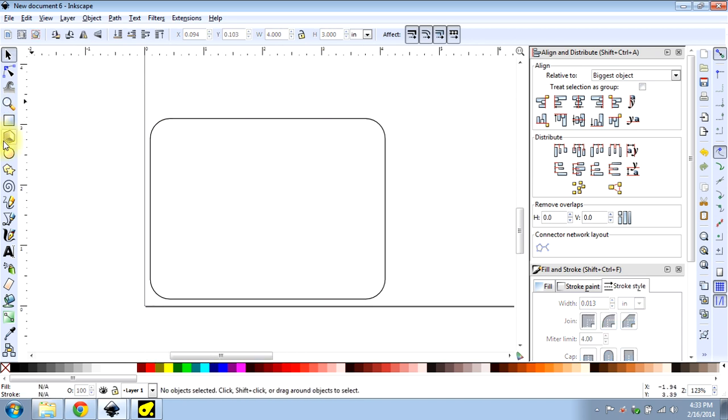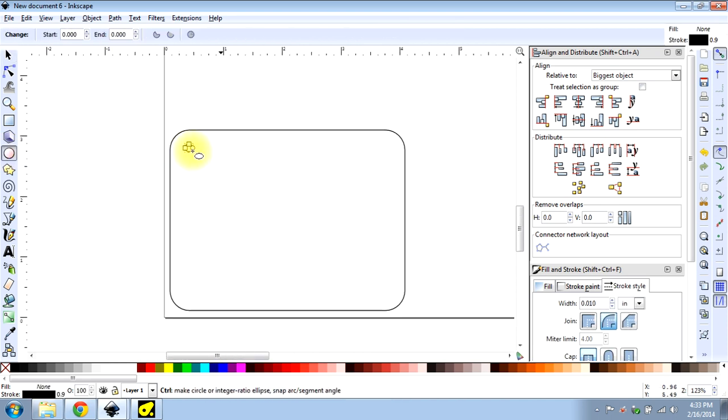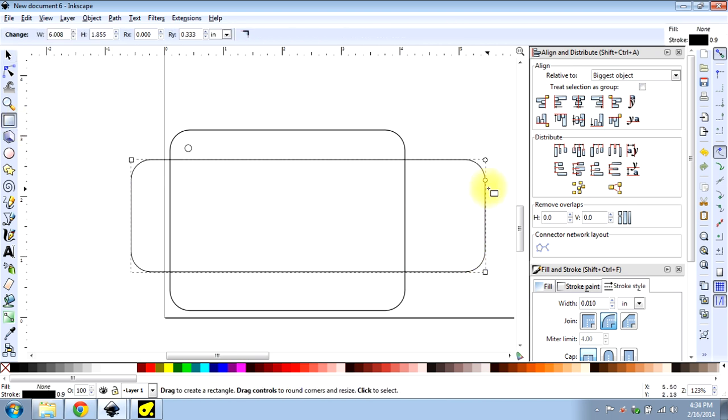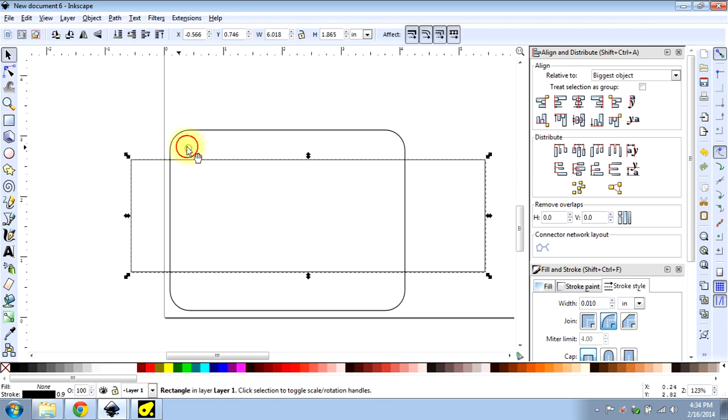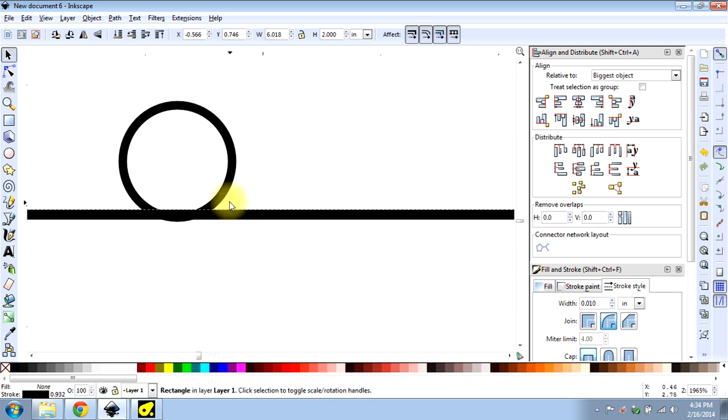And let's say we've got a little doodad we're going to mount to it, like a circuit board or an Arduino board, or whatever. It has 4 holes in the corners, and those happen to be 0.125 inches, 1/8 of an inch. And we also know that they are 2 inches apart this way and 3 inches apart this way. The reason we know that is because we measured it with our little $20 calipers. So here, we're just going to make an arbitrary box, and we are going to make this box exactly 2 inches tall. And this is going to be our measuring stick.